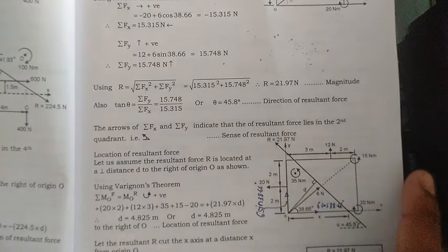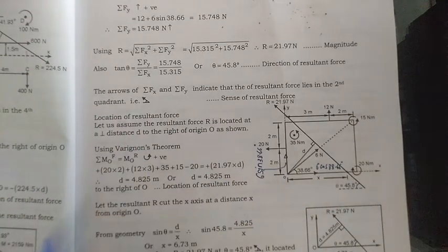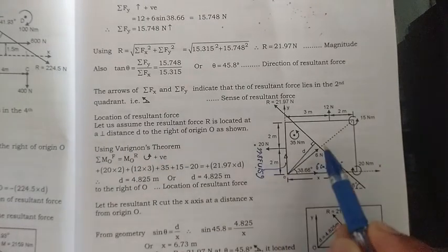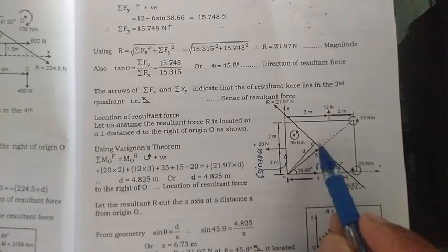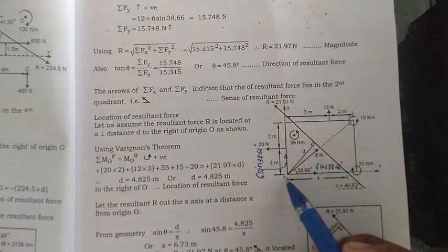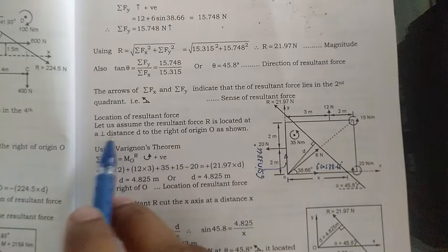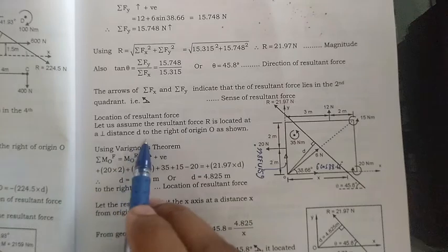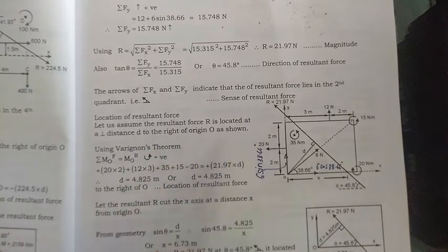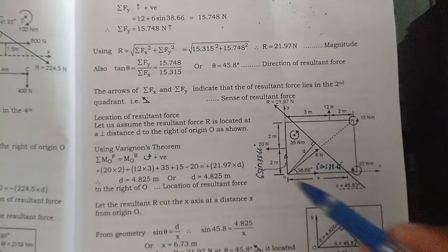Then a very important step is to locate the resultant force. To locate that resultant force, assume that the resultant R lies towards the right side of point O at a perpendicular distance d from this point O. Here this assumption is clearly written. Let us assume the resultant force R is located at a perpendicular distance d to the right of origin O. Now by using Varignon's theorem,